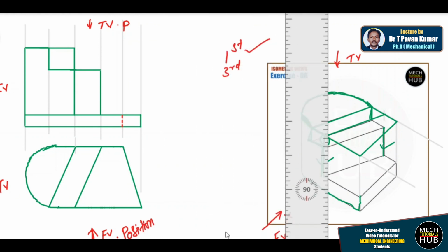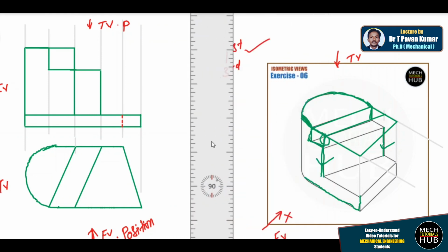and rest you know how to take simple side view. If they asked in the question, simply take horizontals from each and every vertex of front and top, then draw 45 degrees inclinations from the projector lines of top view, then verticals, horizontals, meeting point of vertical and horizontal will give you the side view. Okay, this is how it is going to be. I am trying to explain you the concept followed by how to present it on the sheet of paper.